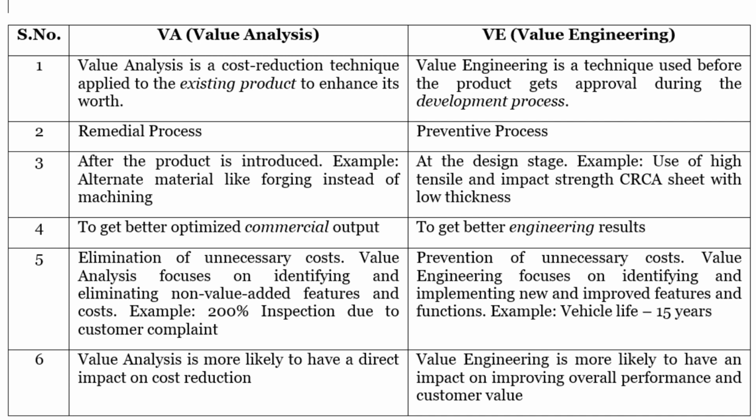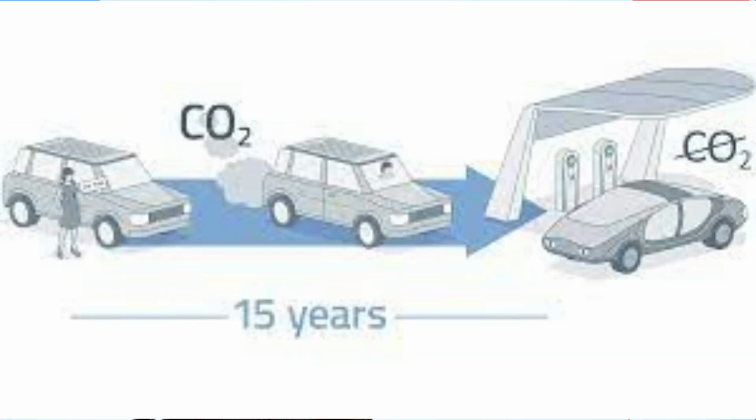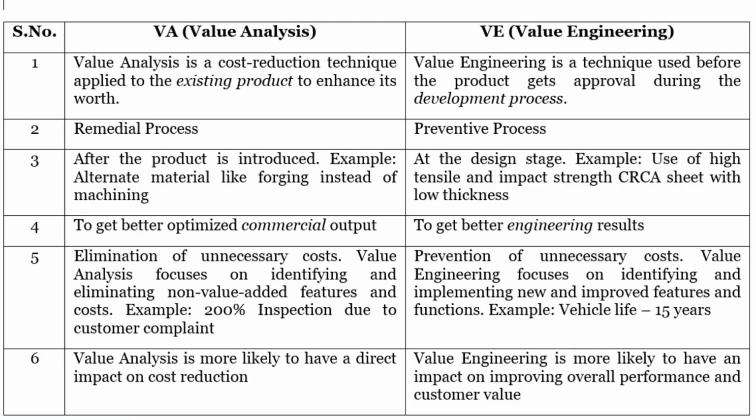Something similar applies to value engineering also, wherein when we are designing a vehicle, we know that, say, in the context of India, the vehicle life is 15 years. If we talk about a diesel vehicle, the vehicle life is 10 years. While designing, we need to make sure that we do not add so much value that the life is 20 years, which is actually not required, because as per the government law, it is 10 years or 15 years. And lastly, when we talk about value analysis, primarily we are talking about something which can have a direct impact on cost reduction. While value engineering is more likely to improve the overall performance and the customer value.